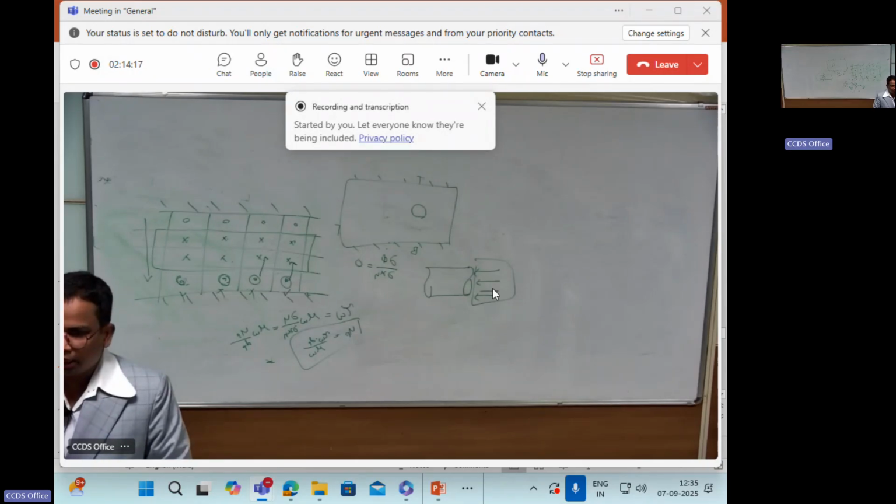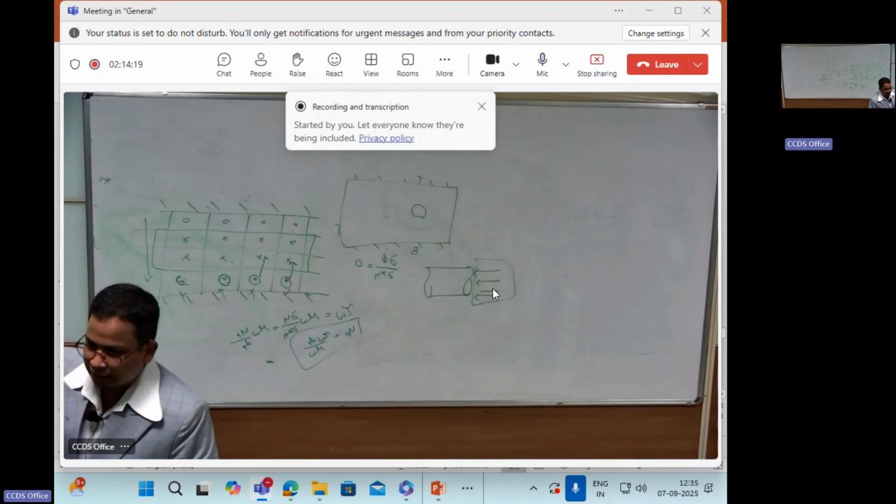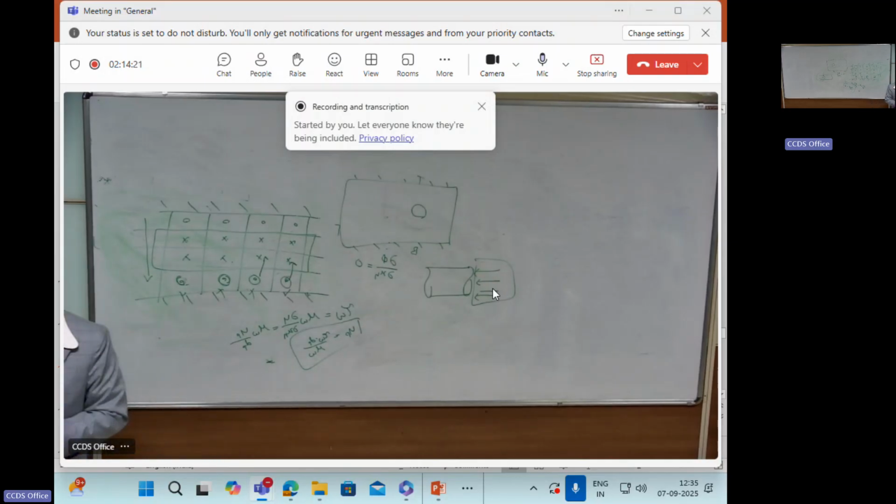Session on K omega turbulence model. In the last session, we covered extensively the K epsilon turbulence model. Now we'll go to the K omega turbulence model. Earlier, we have defined what is omega. Omega is specific dissipation, turbulent dissipation per unit kinetic energy, right?